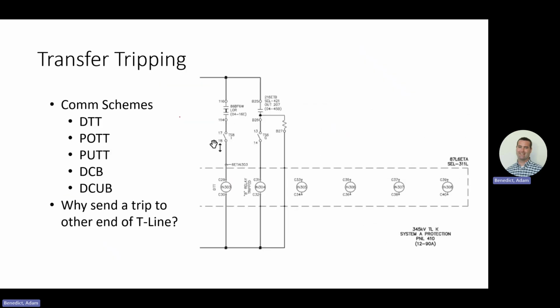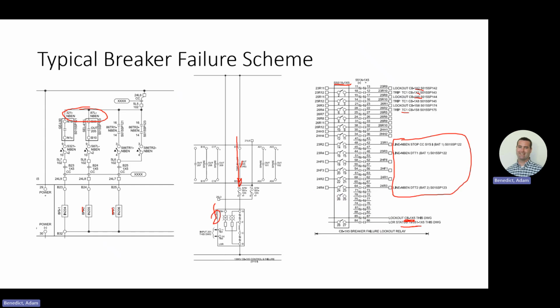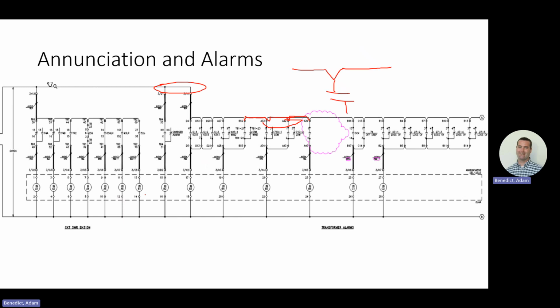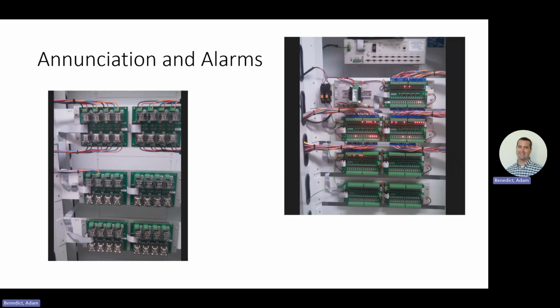Any of these relays, we kind of take for granted because they all accept 10 to 12 solid. But you shouldn't, because especially once you start getting into alarm and annunciation, not every wire will fit. These are pretty delicate connectors, and they're designed a lot for industrial and facilities. But when it comes to utilities, we need to make sure we're using 18 gauge or 14 gauge wire into these type terminals if you're utilizing this type of annunciation or RTU.